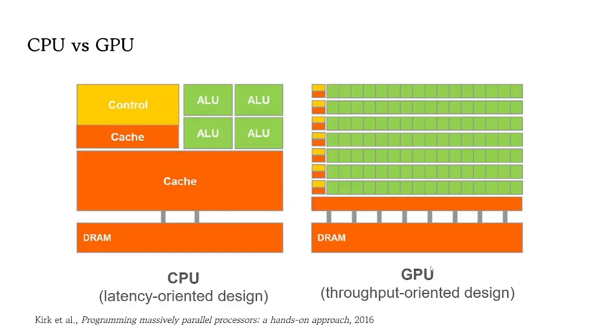There's another aspect with the GPU as well: the kind of computation which has to be done per frame can be thought of as doing the same mathematical operation but on multiple pieces of data. And the designers of the GPU went for the logic that we are going to run a lot of threads in parallel. All of those threads will be simple. They'll run the same sequence of operations on different pieces of data. Whereas for the CPU, the threads are much more complex.